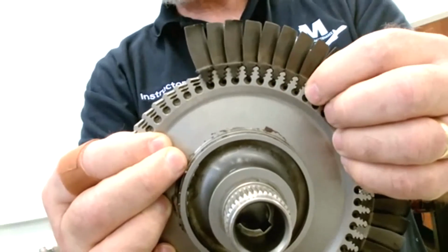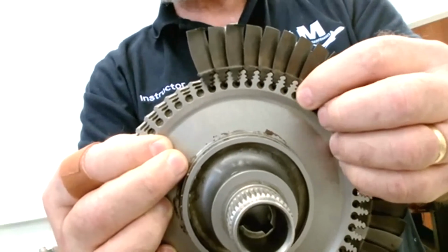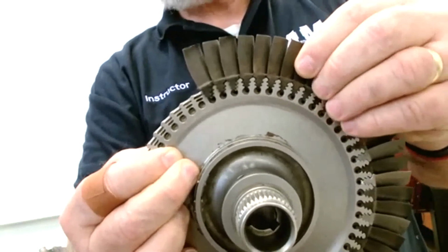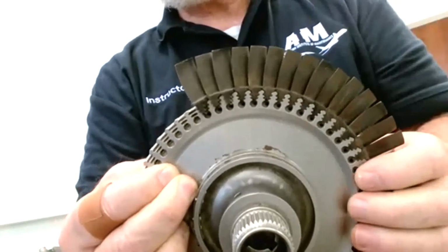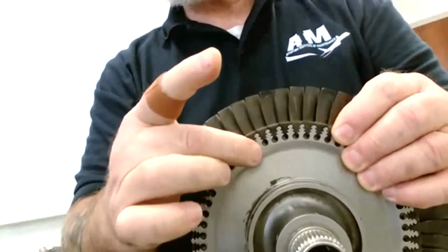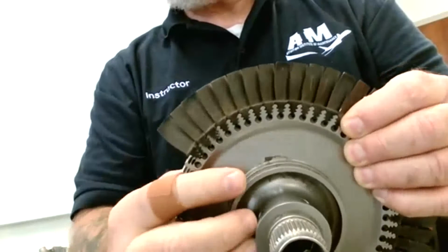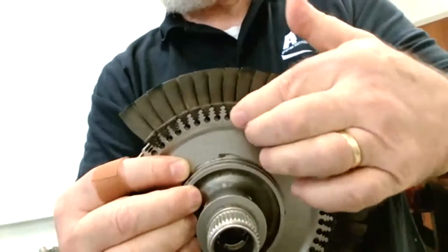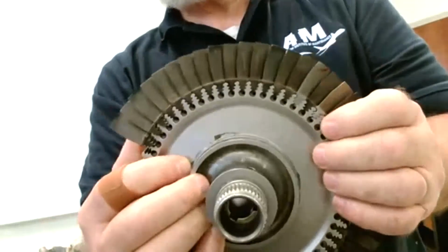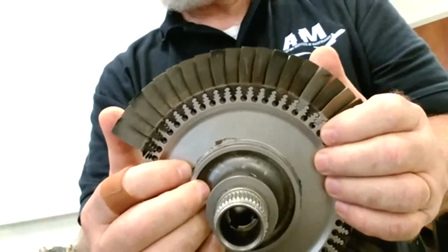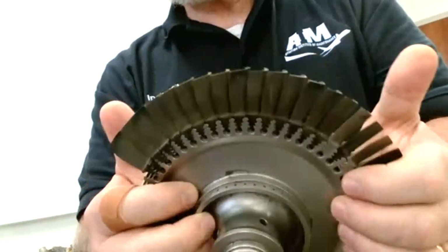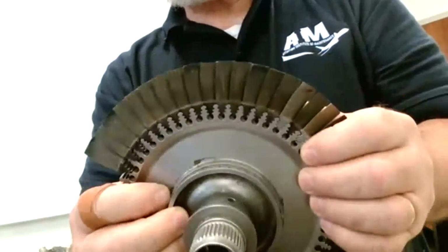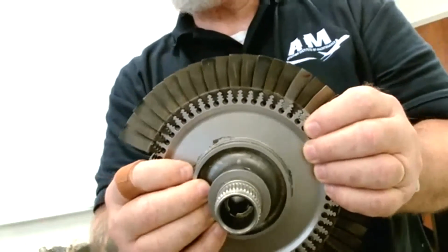And the reason for these is because it has the most surface area to secure the blade in there. Now this stops the blade from flinging out with high centrifugal loads, and then there would be rivets or the blades would be peened in order to keep them from moving axially, okay? So that's what's going on there. We have the fir tree attachment. It is by far the most common attachment process that's used in turbine blades and also many of the compressor blades as well. So the FAA's favorite is fir tree attachment, all right?